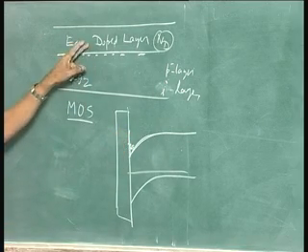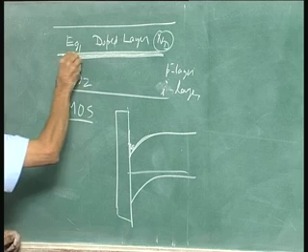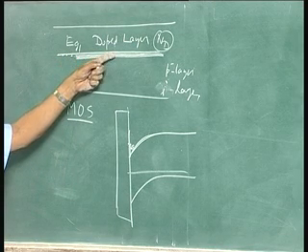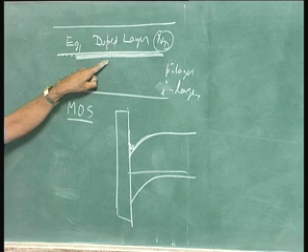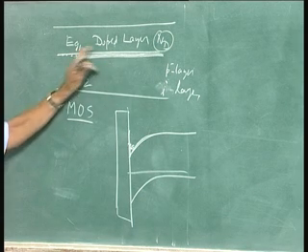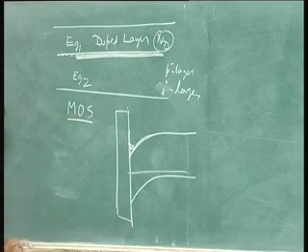When you go from here to here, you will have a notch which will actually collect the electrons here, and those electrons come from the donor level. This is heavily doped donor, this is lightly doped. These electrons experience only lattice scattering. So, details of this heterostructure I will discuss in the next lecture. Okay. It is quite an interesting part actually.